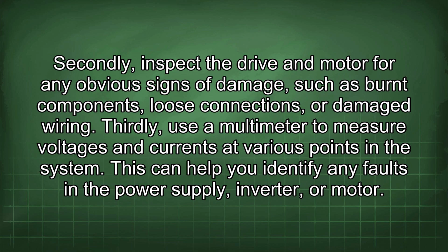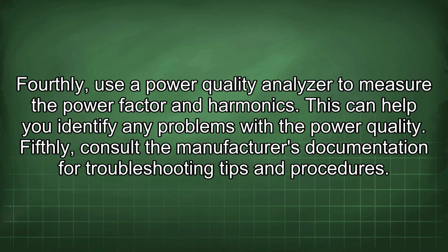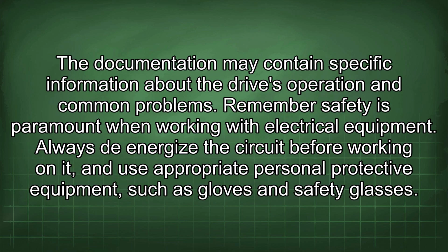This can help you identify any faults in the power supply, inverter, or motor. Fourthly, use a power quality analyzer to measure the power factor and harmonics. This can help you identify any problems with the power quality. Fifthly, consult the manufacturer's documentation for troubleshooting tips and procedures. The documentation may contain specific information about the drive's operation and common problems.